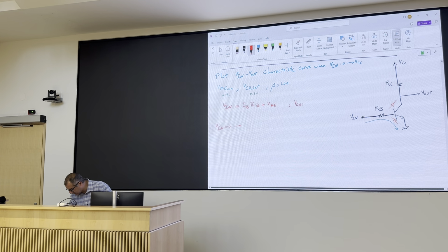So let me write the whole thing, but you already know. So VBE off means reverse bias, and VBC is happily off as well. You can verify this later after you have the currents calculated and everything else. And therefore, you can say that all terminal currents are 0, including IC. And if IC is 0, what is the Vout? Vout is VCC. Yeah. Right? Good.